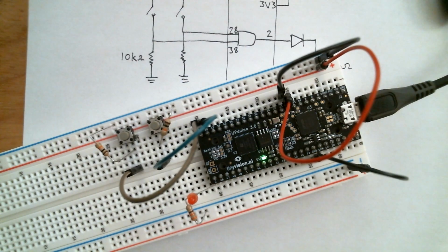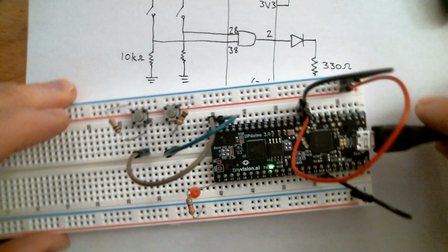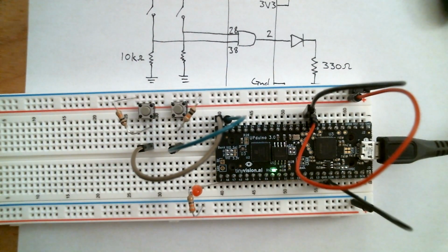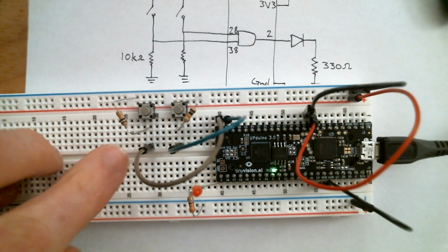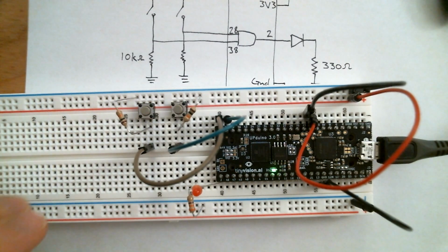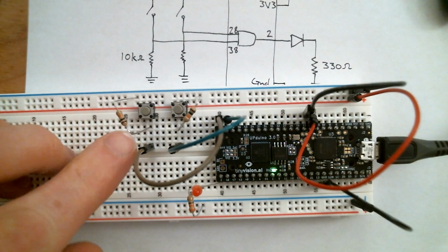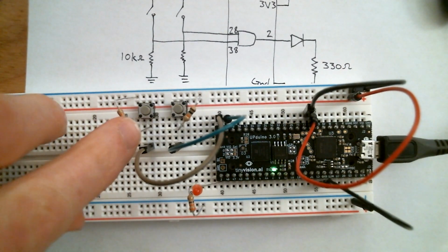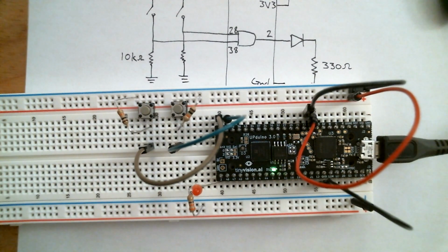If your circuit's not working, then you're not able to get that LED to light up when you press both buttons, or maybe it lights up when only one of the buttons is pushed. The first thing you want to do is go and check that these get a multimeter if you have one. We've got access to multimeters in the lab, and confirm that the value on the inputs actually is toggling between ground and 3.3 volts like you would expect.